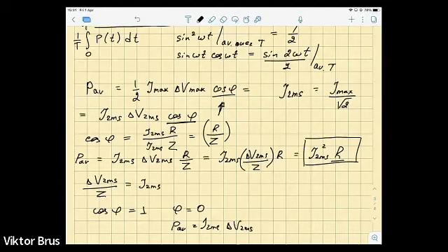And that is originating from the fact that most consumers, like electric devices and equipment connected to this AC electric circuit, possess active resistance and inductance. They are lacking much capacitance. So in order to increase this capacitive contribution to the total electric circuit, it is intentionally added to the electric power system.